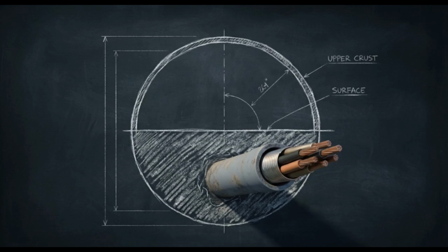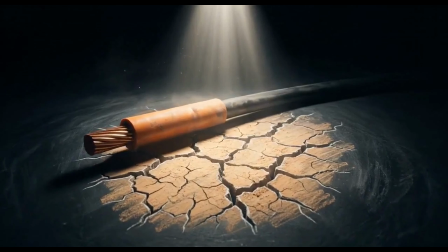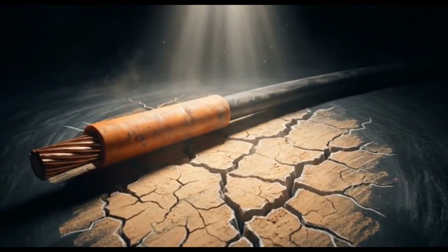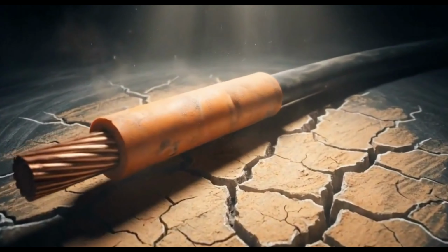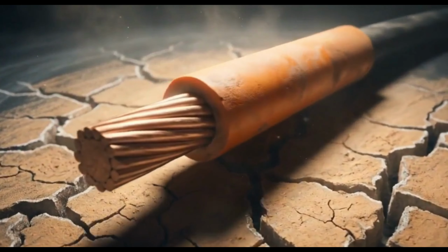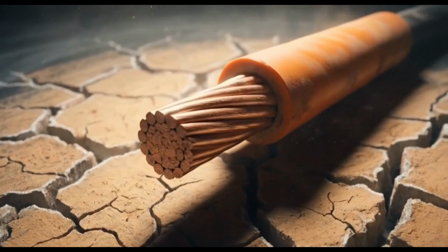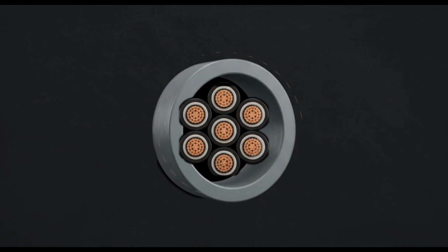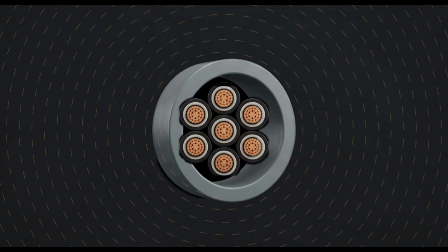The final thermal barrier is the installation medium encasing the cables. Open-air installations benefit from natural convection. However, cables buried underground or sealed in conduits face much higher thermal resistance. Placing cables inside a plastic conduit or burying them in soil introduces massive thermal impedance. The surrounding earth and the conduit walls act as physical insulators. They trap the I²R heat within the installation site, preventing it from migrating away from the conductors.